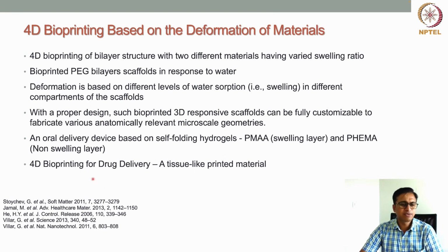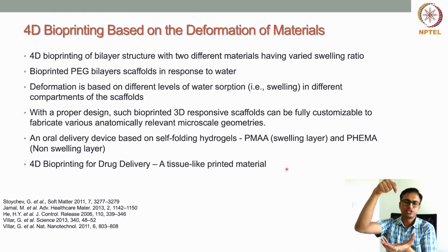Similarly, Wheeler et al. have come up with a tissue-like printed material using this 4D bioprinting concept for drug delivery applications. In this case, they have used a concept called emulsion, where water droplets are printed within a bigger oil droplet. So they have a bigger oil droplet where the surfactants are dispersed. Then they introduced a micro nozzle within the oil droplet and printed water droplets within this big